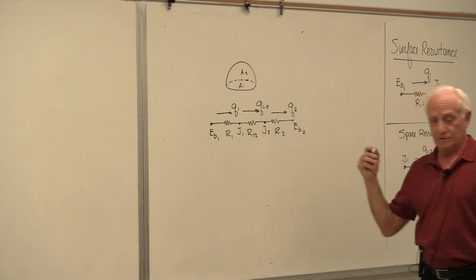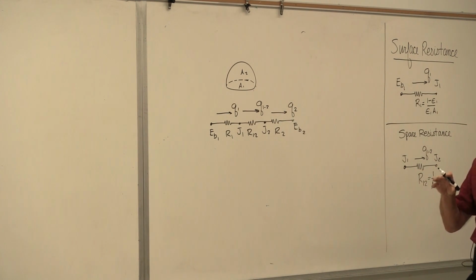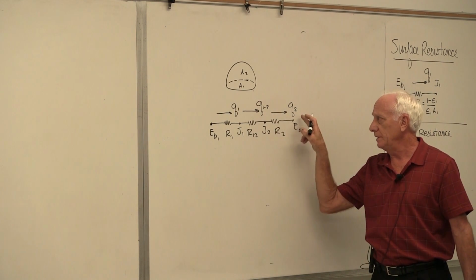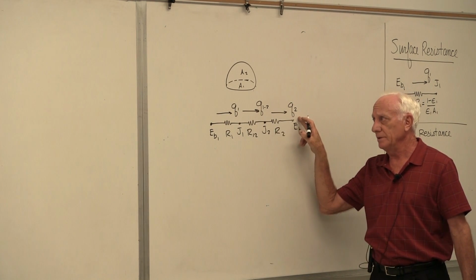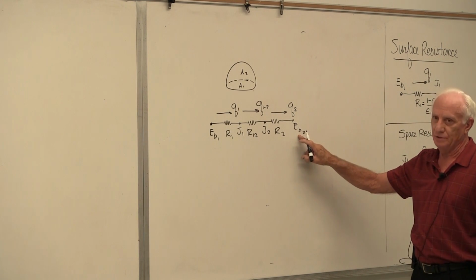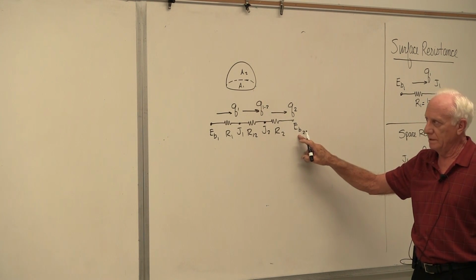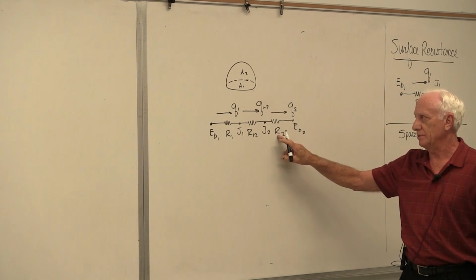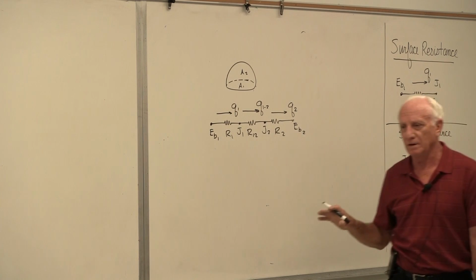And we found this is a series. Two surface enclosure, they're all in series. And if you want to find the Q, since all the Q's are the same in series, Q1 equals Q12 equals Q2. The way you find the Q is you take EB1 minus EB2, which you know because the temperatures are given, divided by R1 plus R12 plus R2. And now you've got Q, end of problem.